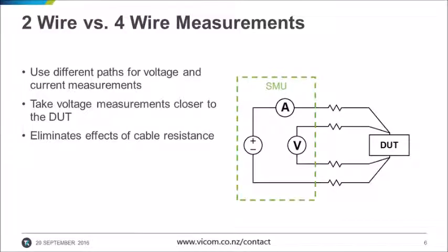The simplest technique to reduce error in a DC voltage measurement is to use a 4-wire setup. The goal here is to eliminate the effect of stray impedance in the cabling. The fact is that all cables have an impedance, and that a current through that impedance will cause a non-zero voltage drop over the cable that can lead us to believing there is more voltage across the device under test than there actually is. This becomes extremely apparent when measuring very low resistances or when sourcing high currents.